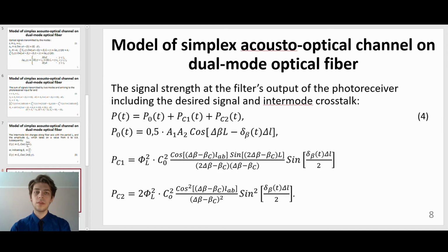Applying equation 3 to equation 2 and using the known formula for the cosine product by the cosine sum, we arrive at standard integrals. As the signal comes to the square law receiver input, we take the square of the sum signal at the far end, considering the integration results. We ignore terms up to the second order inclusively, embed the low frequency component, and exclude the steady one.